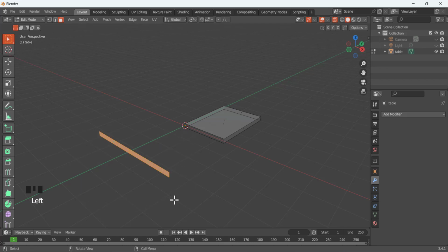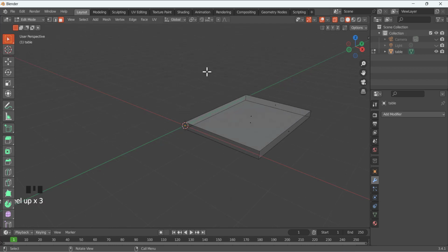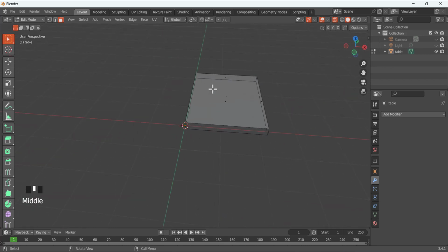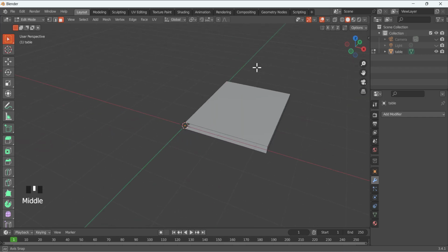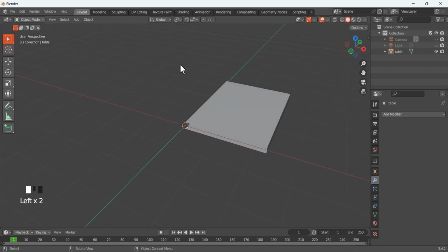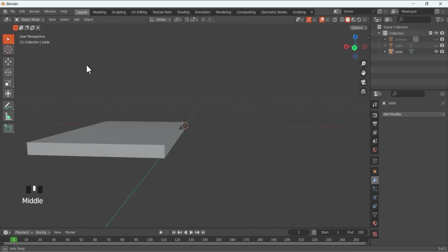These faces are not selected. Again, select them and press X to delete these faces. Now we deleted all the other faces, and just one portion of this object is here. Now deselect the X-ray, and you can see we have only one portion of this. Now go to the object mode, and we have this object like that.